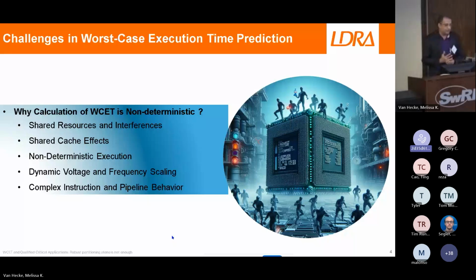And there are also other characteristics that can make our timing even worse, like the voltages, the temperatures, and even complex instructions can affect the behavior of the program. So how can we certify multi-core applications for safety and also airworthiness, or flight software?